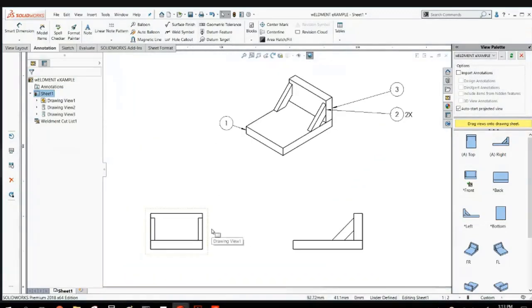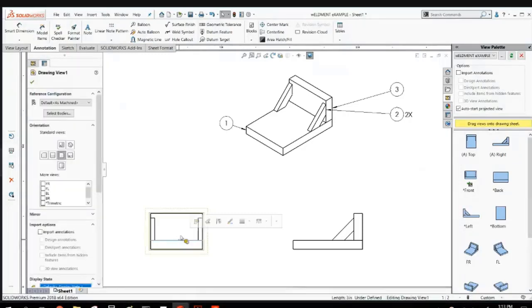And then this is truly a weldment, so I need to tell them how to weld it together. I'm going to show you in the next example how to put in weld beads as features inside of your part, but it's not necessary. You can just put in weld symbols as if they're annotations in a drawing. A lot of times that's what people do here.